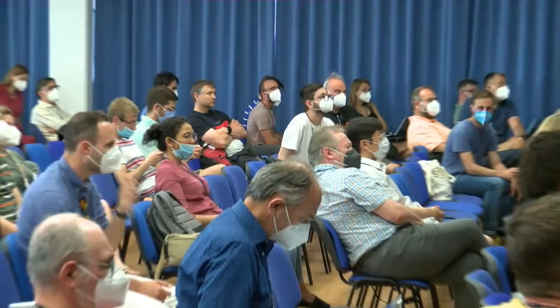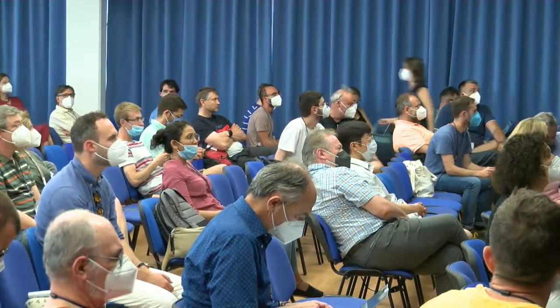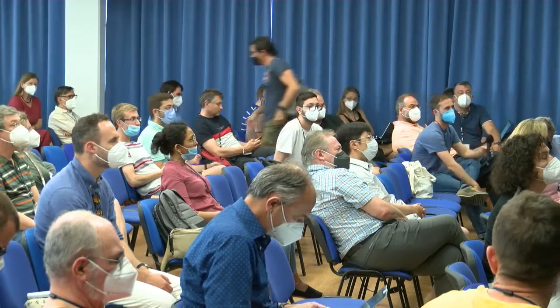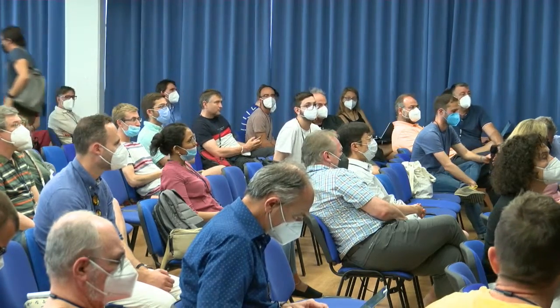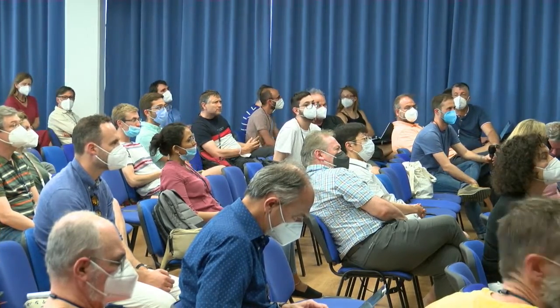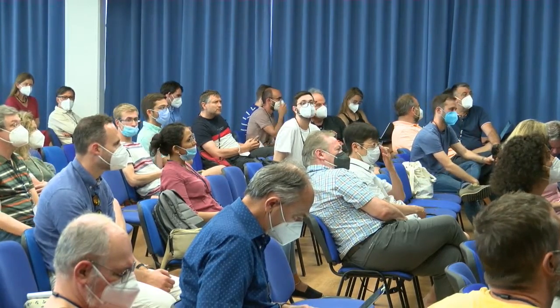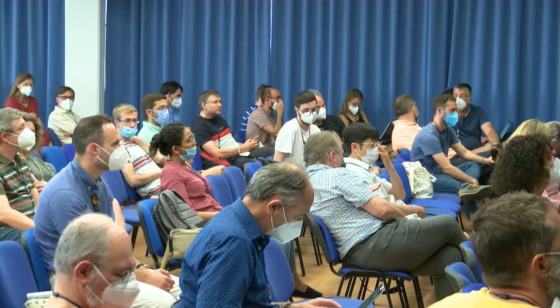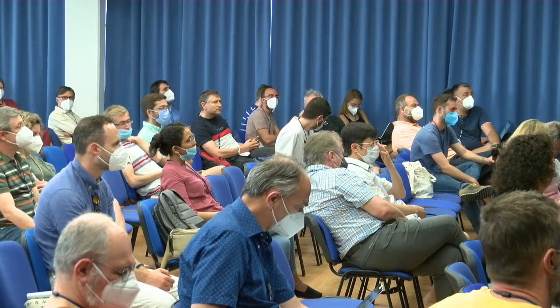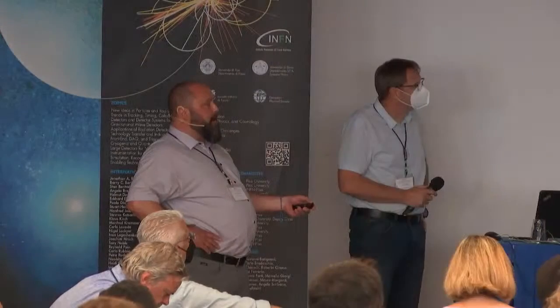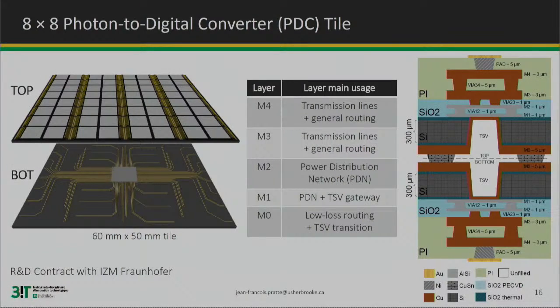There you have two silicon vias at the depth of 300 micron, which I consider quite challenging. What is the aspect ratio of the silicon vias? And are you already having samples, or is this a wish? No, this is not a wish. I believe it's 10-to-1 or 8-to-1. I would have to check with my grad student who's leading this, but I believe it's 8 or 10-to-1.